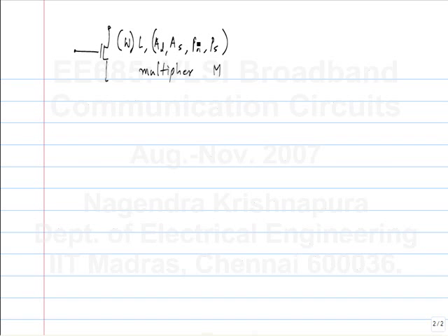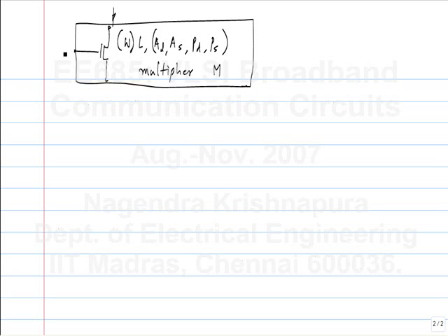Do you know what it does? I think this is what it does. Okay. Because there are two parameters. One is the number of fingers. That also can be specified, I think, in some varieties of SPICE. And sometimes you just use a multiplier. The multiplier M is used to indicate that if you had a single transistor, there would be some certain currents into the terminals. When you have M, you make that M times that thing. So everything does get multiplied. Okay. But I would still advise you to check the manual just once.